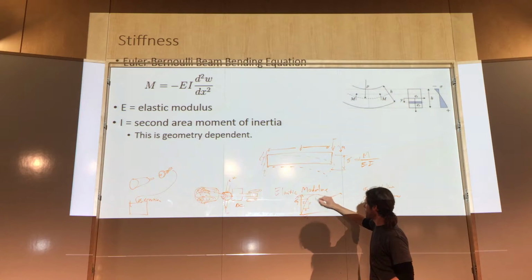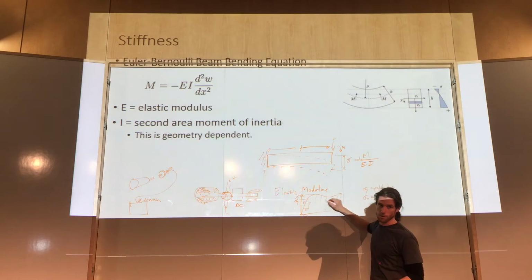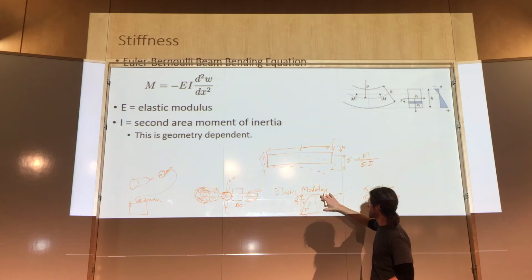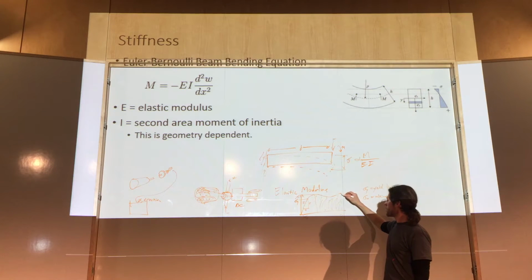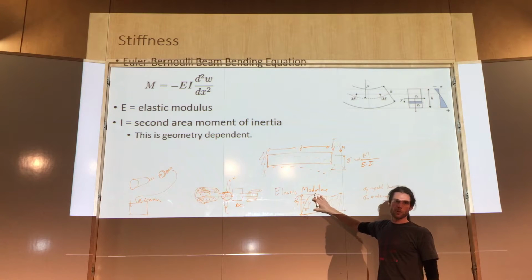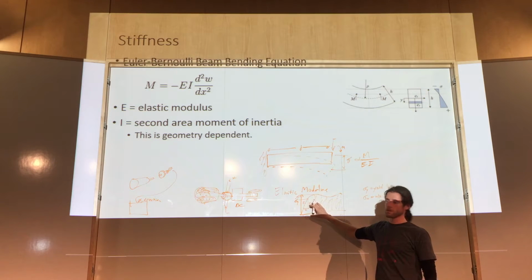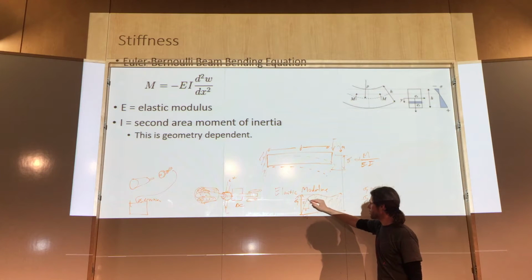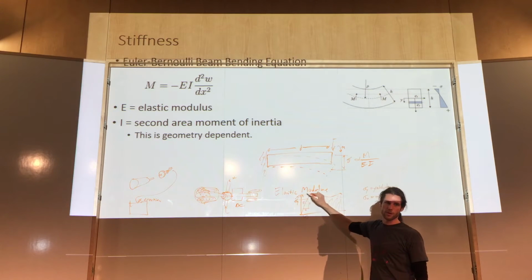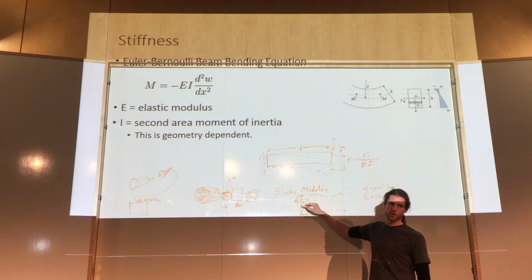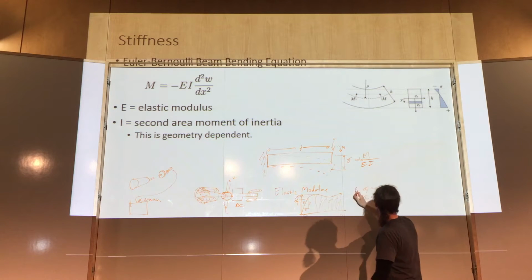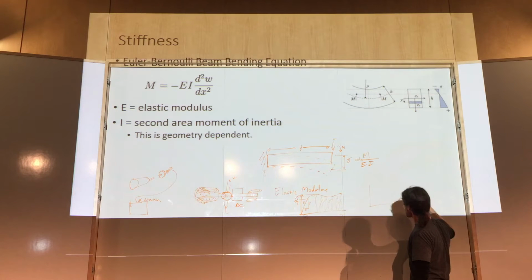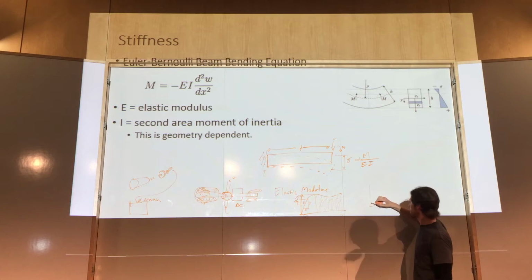All this time, you're absorbing energy, which is something to keep track of if you're interested in absorbing energy. You're putting energy into the system, but it's not necessarily useful for traditional machines where you want everything to retain the shape you originally wanted. Every material is going to have different properties, but at least engineering materials have some zone around here. Wood has it, plastic has it, ceramics have it. If it's a really brittle material, say a ceramic or glass, it might look like this, and then just break right off.